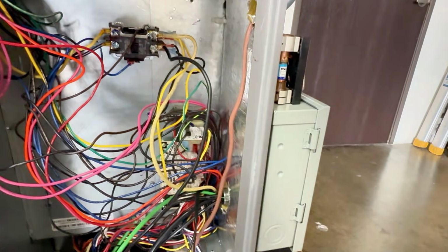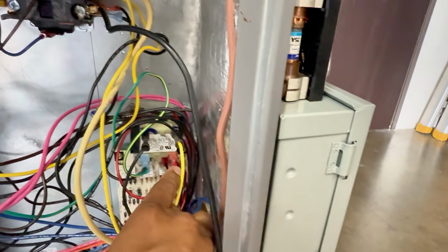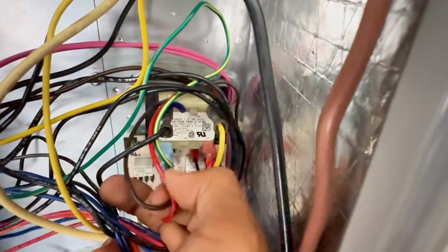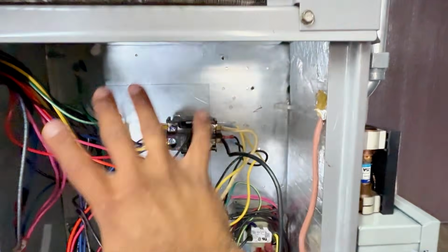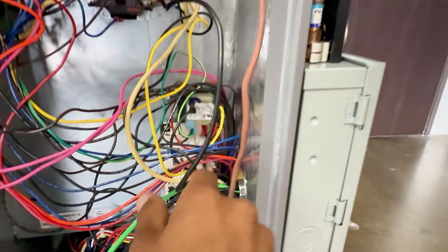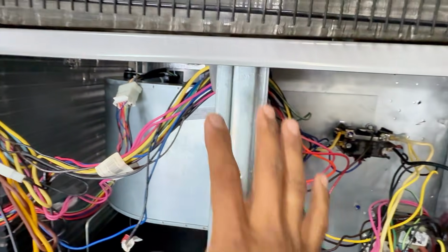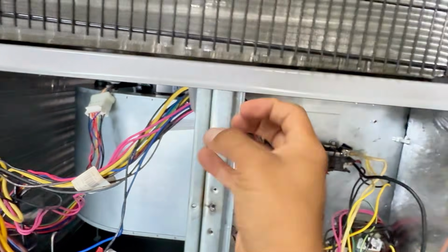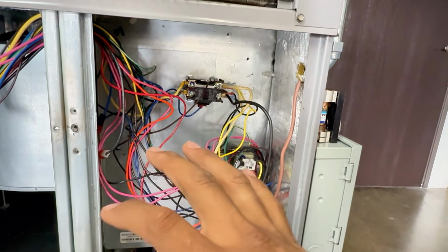And I'm going to show you right now an example. But just to emphasize the point, you got 24 volts coming out on the red. You have a brown one, but then the ground is also on your common that goes to the actual screw on right there to the metal. So the whole unit is common. Think about it. That 24 volts can travel through your pressure switches. It needs to go to your contactor coil. You got a low voltage going to your ECM motor. There are a lot of points where it can strip and touch the metal. And that's good because it's going to pop the fuse. If that wasn't grounded, you can have weird voltage drops.